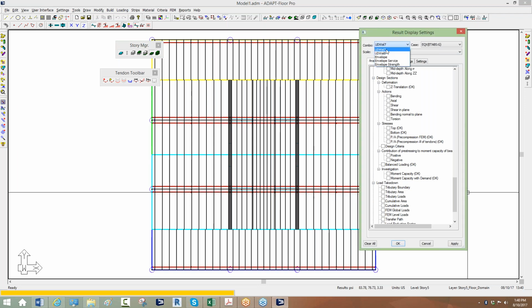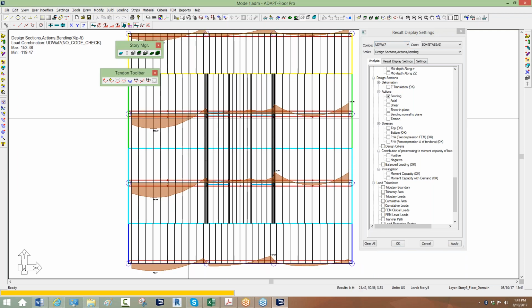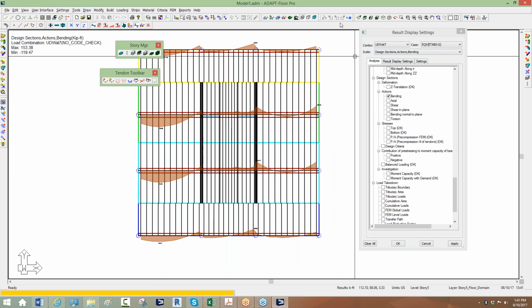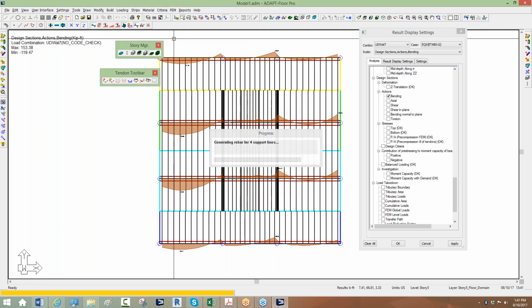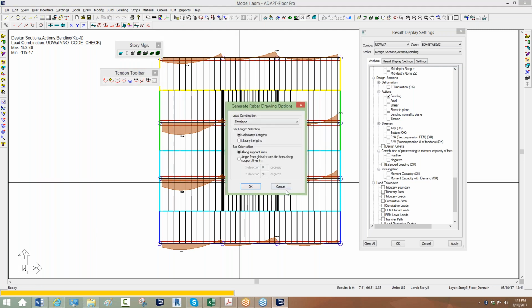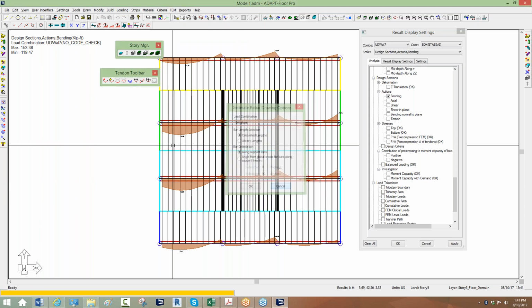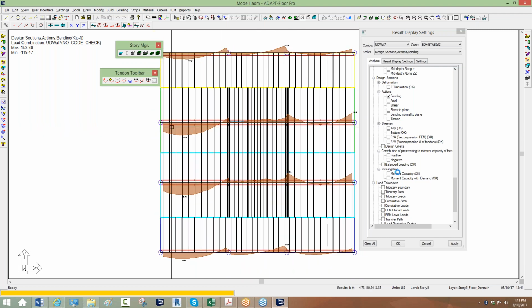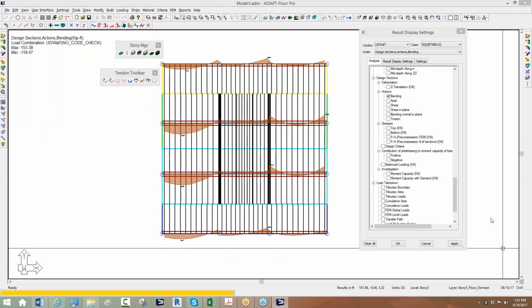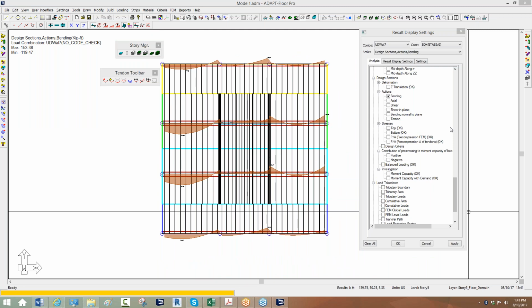you can see that the program produces, for example, bending actions along the strips. These are the bending diagrams relative to that combination, which included several sources of load case solution. And ultimately, we might want reinforcement for the slab relative to those combos, so we could go ahead and generate rebar for the envelope of that set of combos. Now it says no rebar is needed. We have PT in the slab, so the PT satisfies the requirement for the reinforcing in the slab. Okay, so that's the second workflow.